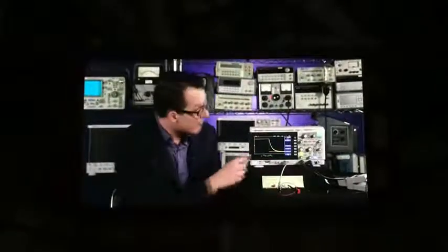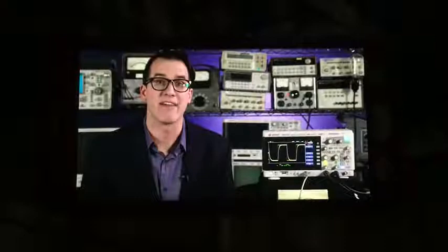And you can see if I zoom in here, this region, my capacitor is charging up. It's resisting that step up in voltage. Here my capacitor is starting to discharge, so all of that charge stored up when the voltage was high is slowly trickling out of my capacitor after my source voltage has already gone low. So if you see your system resisting voltage changes or adding some charge back in after the voltage has turned off, you know that's a capacitive effect.